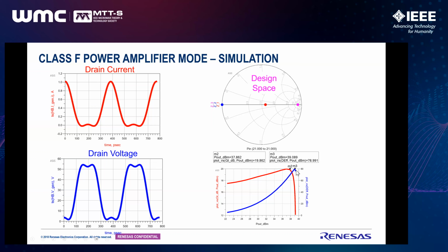Well, you might ask why it is 80%, why it is not 90% as theoretical. Well, a practical device is going to have its knee voltage. By knee voltage, you typically trade off 5 to 7%. And another point here is that the third harmonic is not intrinsically a perfect open, so it's still representing some loss there. So you still end up having around 80% compared to 66 to 67% of a realistic class B efficiency performance.